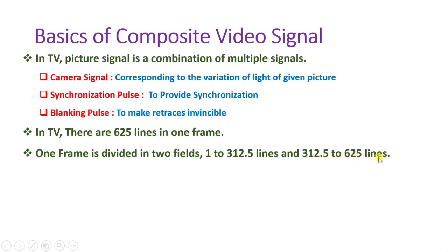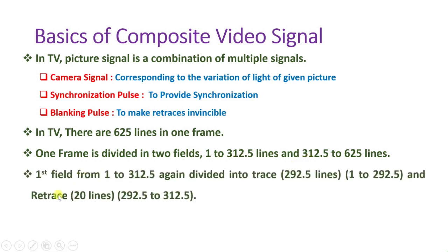With regard to time, the signal amplitudes right after blanking in Figure 7.2 show information corresponding to the left side at the start of the display line. Just before blanking, the signal variation corresponds to the right side. The exact information in the middle of the display line is the half time between blanking pulses.